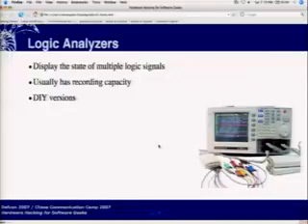When you're using a logic analyzer, you can look at all 4 of those lines and see how the chips on the board are communicating, and whether that's where the bugs are in your code or your layout or whatever. These peripherals we're talking about are on a single board. This would be for communication between one chip and another. I don't think that I2C is usually used to communicate between individual devices like a computer and a router.